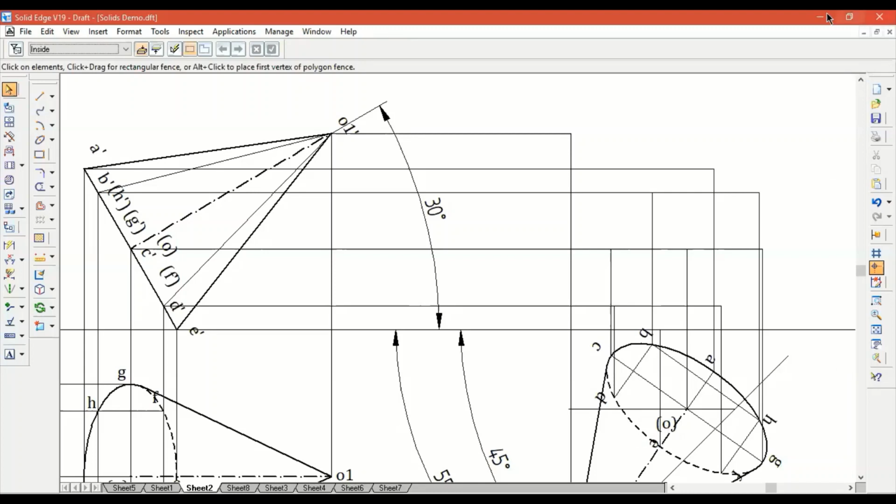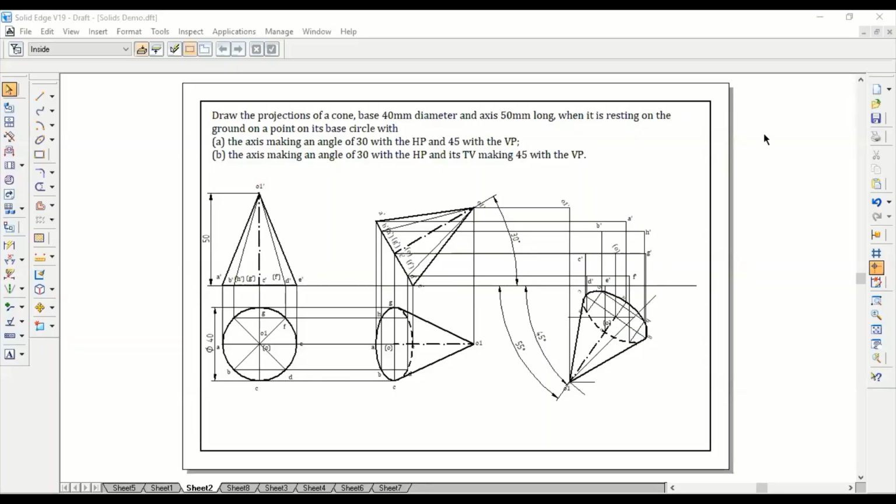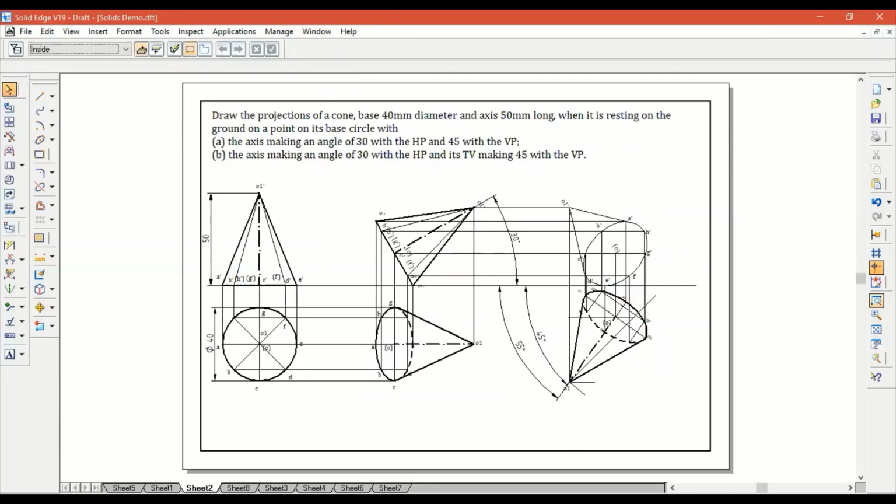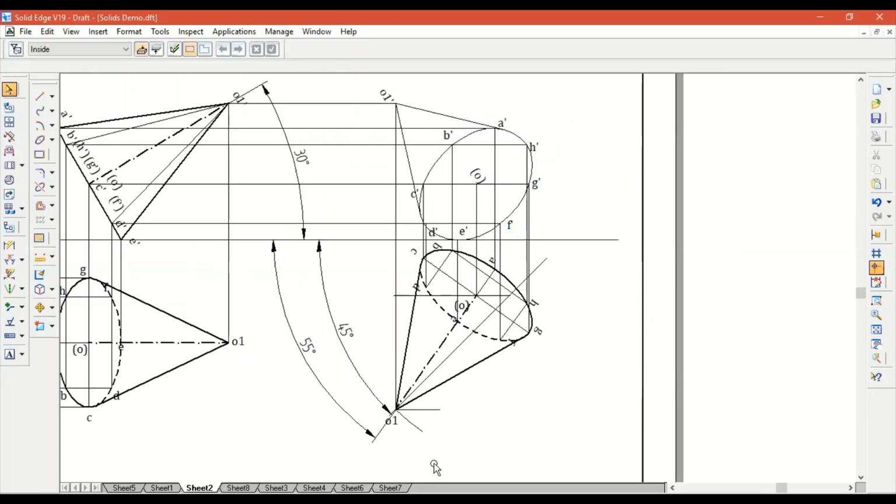Okay. So magic time. So I'm back with the nomenclature, as you can clearly see here. So I'm just going to zoom in. So obviously, once the curve is drawn, we need to find out which is visible and which is invisible. So clearly, the apex is closer to the observer when he's looking or she is looking from here. That means I'll have to split the curve into two pieces. So again, I go to split, select the curve, select one endpoint of intersection, which is there, do the same for the other, and you're done.